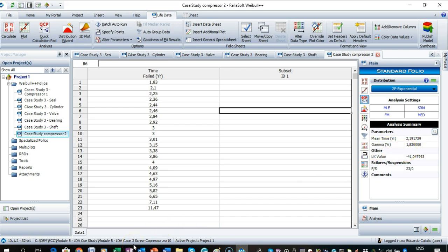And then as we look at the compressor, as we use the exponential PDF, we do not get any trend of failure, and that is one of the very important issues when we assess such equipment. So the result of the exponential is because we have different patterns of failure in these components, and we mix everything up to predict the reliability at the compressor level.